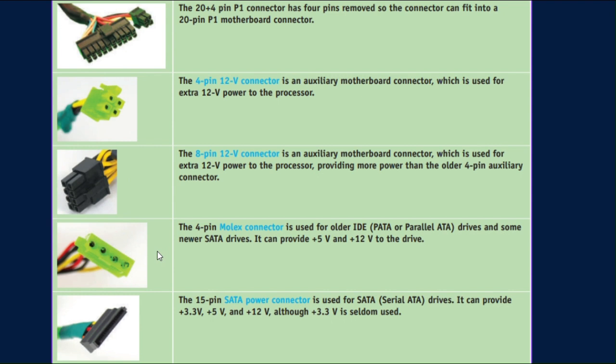And this is also the 4-pin Molex connector, used for older IDE drives and some newer SATA drives. It can provide 5 volt and 12 volt to the drive. Now the 15-pin SATA power connector is used for SATA drives. It can provide plus 3.3 volt, plus 5 volt and plus 12 volt, although plus 3.3 is seldom used.